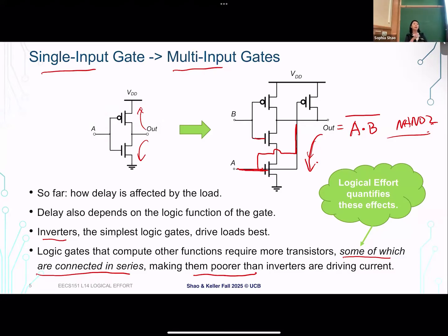You think about whenever we do circuit analysis, right? Even, we'll talk a little bit later, when we look at the pull up path, there could be different scenarios, right? You can have maybe one signal pulling up the circuit, or you can have multiple signals pulling up together, right? Whenever we do circuit analysis, we're looking at the slowest path, because we want to make sure even the slowest path works, right? So here we're looking at the slowest path. The slowest path is basically whenever things are connected in series, and how we actually factor that.